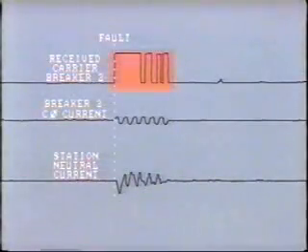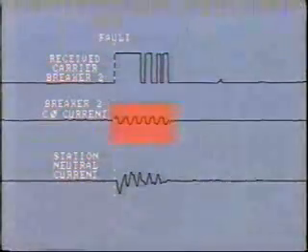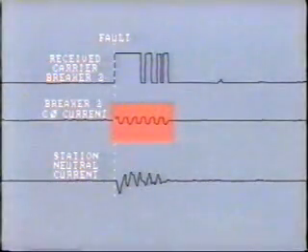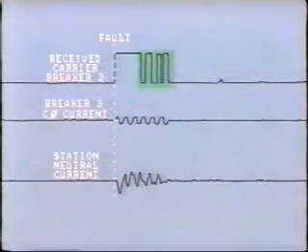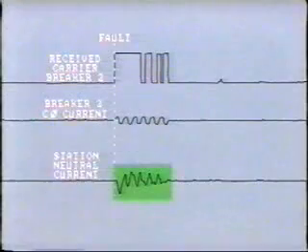Here are traces of the carrier signal that was transmitted from breaker number 2 during the fault and the C-phase current seen by breaker 2. About 3 cycles into the fault, interruptions or holes begin to appear in the carrier signal. The holes are due to the extreme distortion in the station neutral current, that is, the reference current.